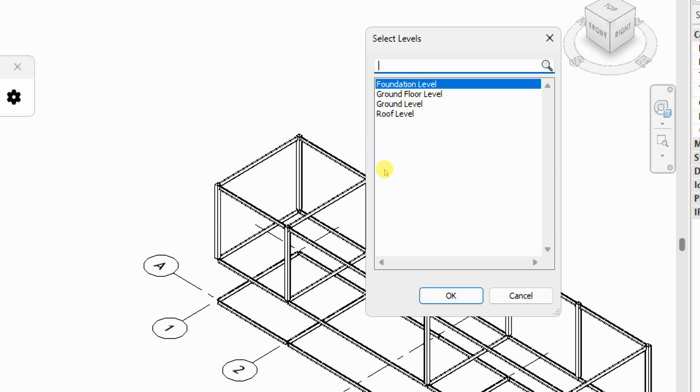So if you are doing a multi-story structure, let's say you've gotten some hostel project you are working on, and the hostel project is about 4 stories or about 6 stories, then you have to take your time and model the columns on one floor, model the beams on one floor. Then when you are done, you can copy them and paste them on the subsequent floors. And if there's the need for you to edit some of them, you can take your time and edit some of them just to speed up the work.